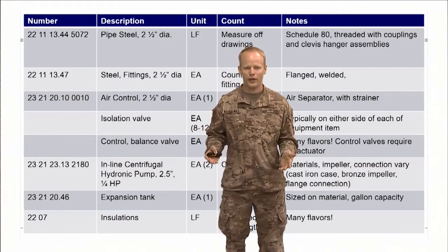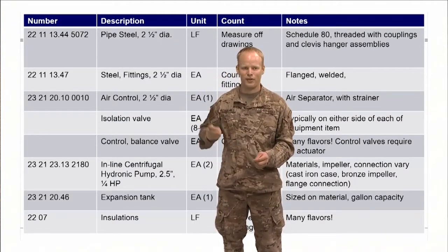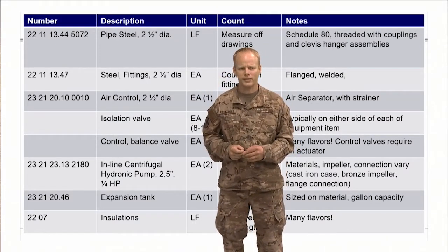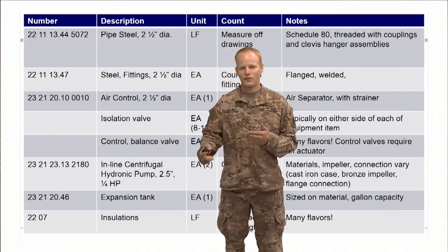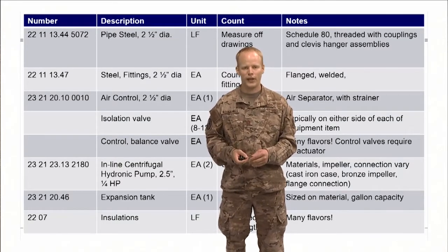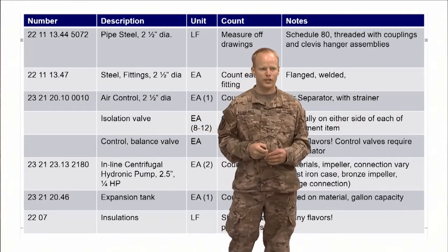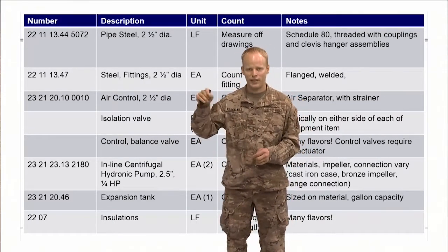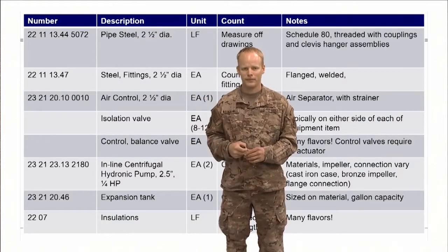Like if they don't put an isolation valve on there, well, I'm kind of putting a bug in the back of your mind that, oh, Captain Westley said something about isolation valves. But if they don't include it, unless you're the mechanical engineer, you're not going to be the one to catch it. Just go on there and count the valves. Just count each little step on there and just build a list. And if there isn't a diagram on there, a note saying what this is, talk to them.